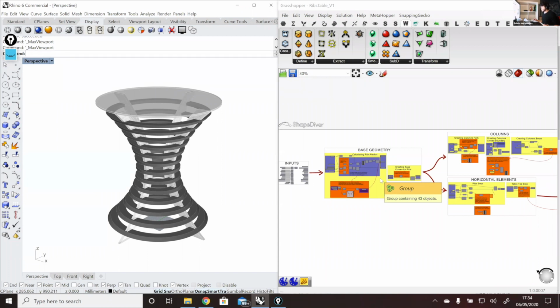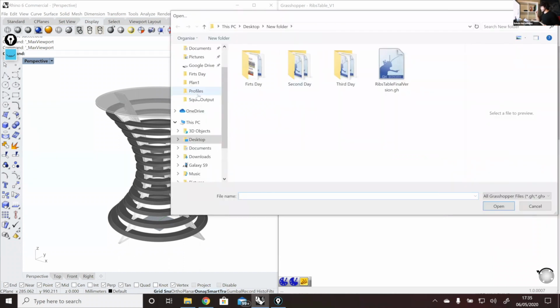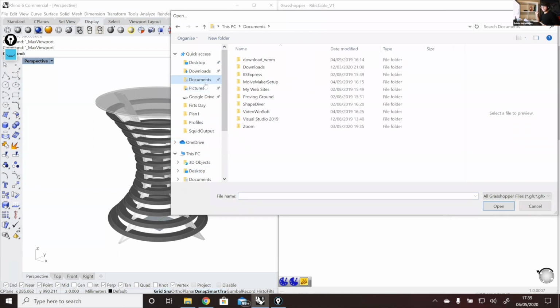So what we normally do is, first of all, for creating the actual curves, we have a C# component that creates meshes and curves from input text, but internalized ones. So instead of creating meshes from scratch, one solution is that you could have, for example, the alphabet in whatever font that you need, and then from that you can pick your meshes. So if we check here, let me find it. Basically we have stored the whole alphabet with the meshes, and instead of creating the mesh from scratch, you pick all of the different parts of your engraving, and then you would, for example, create just the hole in your piece of geometry, and create the engraving.